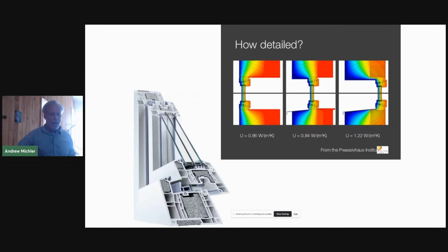And so we want really high performing windows. Typically, they're all triple pane. They use spacers that are not made of metal, meaning what spaces the glass units apart is not metal, but a material that is quite resilient to loss of heat. And then they're put into frames, and they look complex and kind of crazy, but it makes it a lot harder for heat loss through the entire building system. Then the windows are sealed typically about three different times. On the outside, there's one seal. There's a seal in the middle and a seal at the bottom.